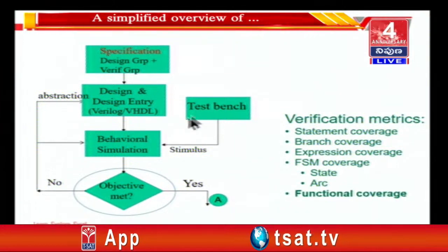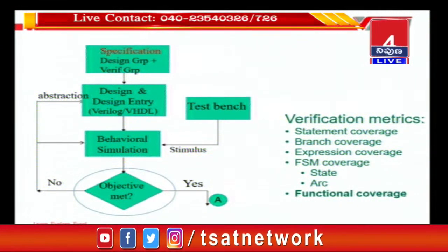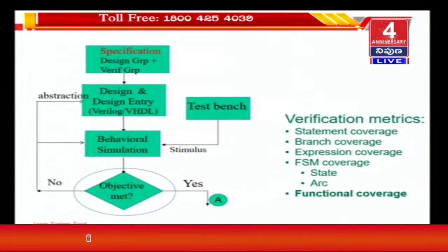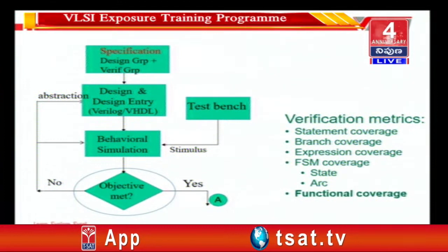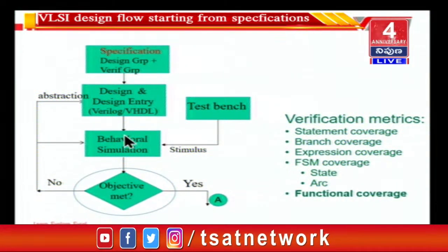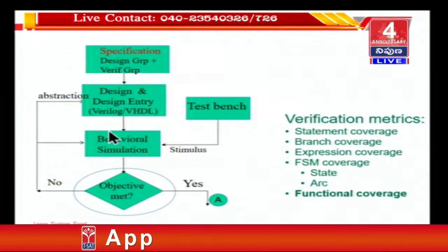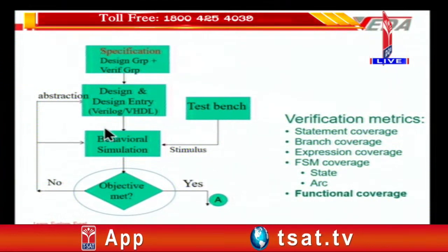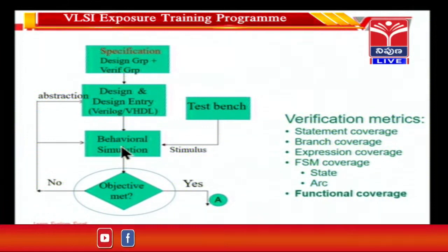Okay. So verification is done at the block level, and then later on it is also done at the top level. Top level means you integrate several blocks together and then perform a verification at the top level to find out whether these blocks are interacting correctly or not. Each of these blocks may be doing its functionality properly, but if they are put together and they are not interacting properly, the communication between the blocks is not correct, then when the blocks are integrated together, they will not work correctly. So that top level simulation is also done at a later time, but here this block level simulation is done.